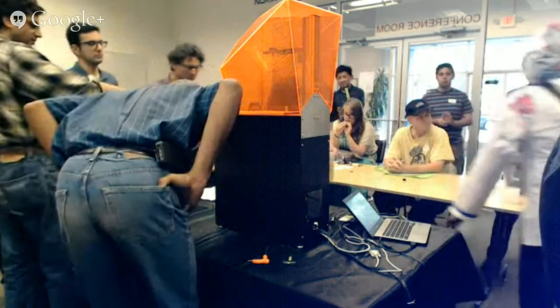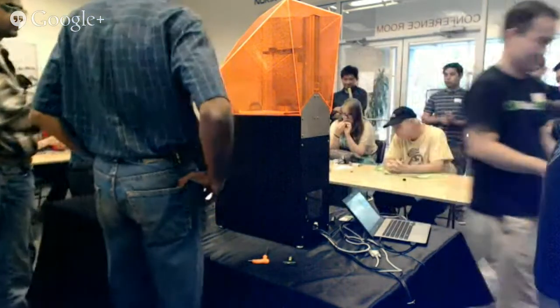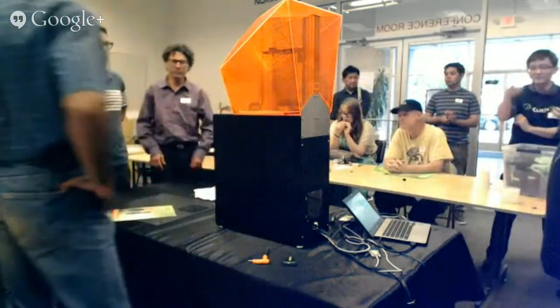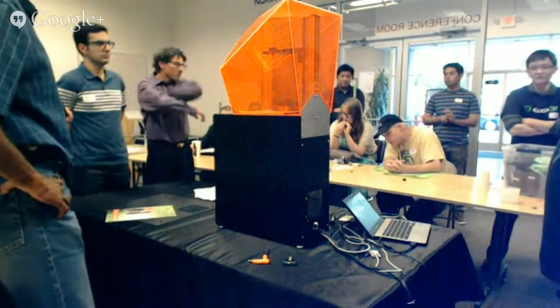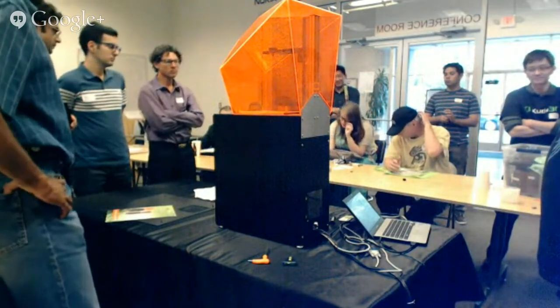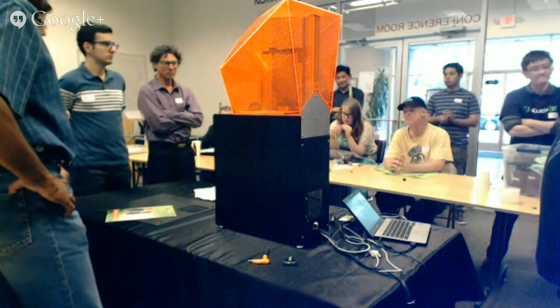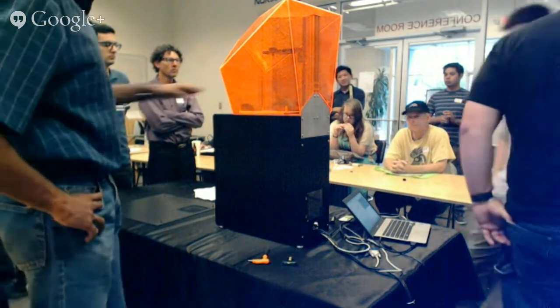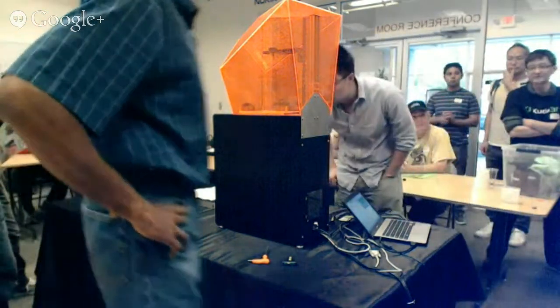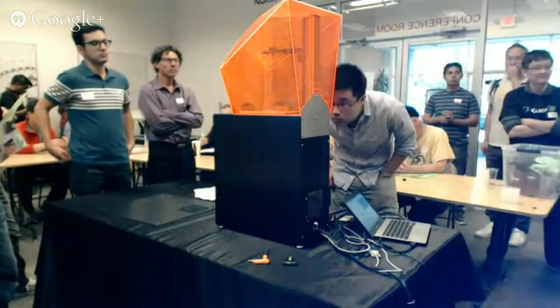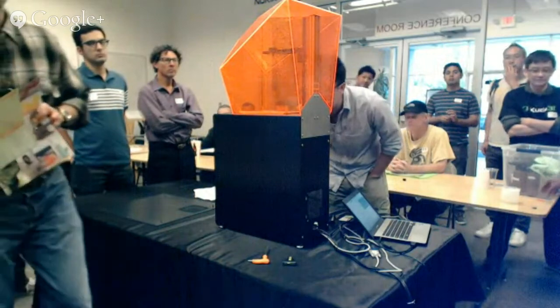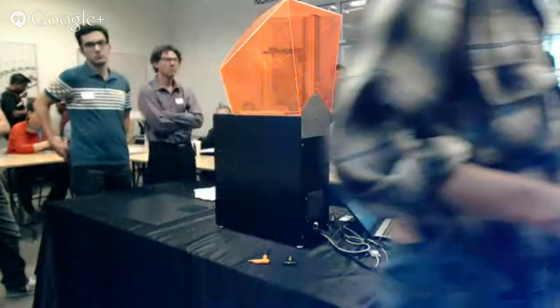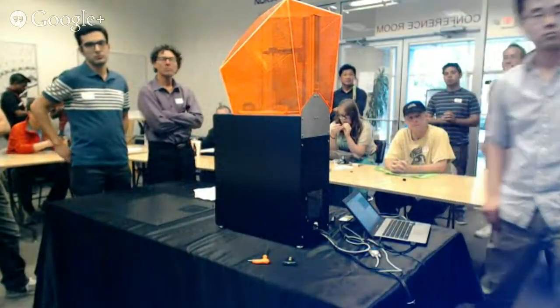violet and higher. Violet is ultraviolet. So our projectors put out mostly around 400 nanometer light. Resins are reactive generally from 350 to 420, and we want to block that. So this guy's pretty well blocked. You can see that he's on stilts. You can see all the stilts. This guy, not so much. Where are the stilts? They're gone, because it's shot through.